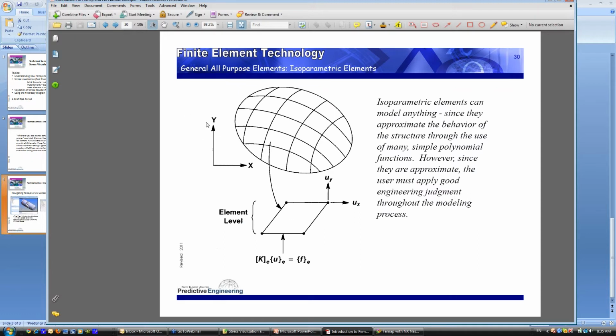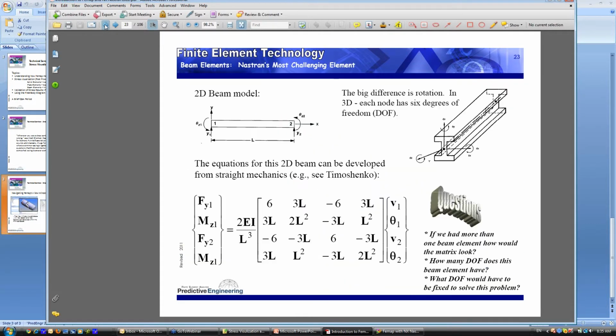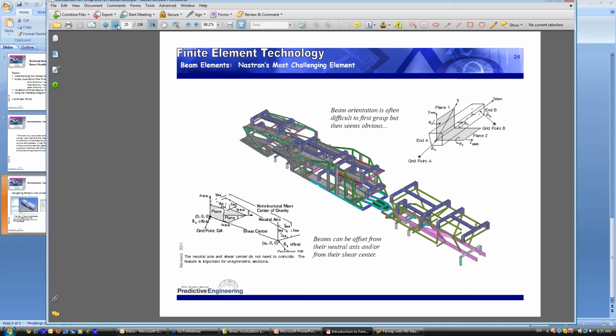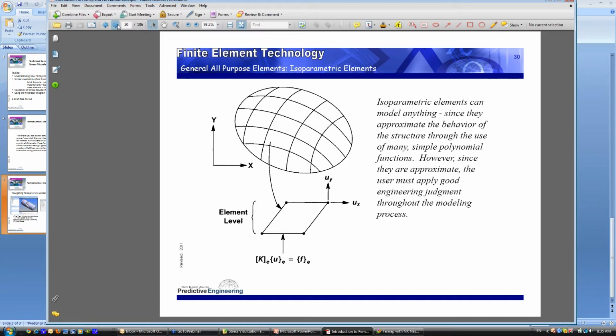Isoparametric elements. The majority of modelers out there, we're meshing plates, we're meshing solids. And then, of course, there's a few that are doing beams. And beams are exact. I'm backing up. Beams are exact because they're using exact formulation in 2D. Everything else, isoparametric elements, it's always a punt. There's tons of approximations that go in to capture the stiffness matrix of a structure because it's a finite element, and you're breaking up your structure into these finite elements to capture the deformation response. And that's done for surfaces and solids via the isoparametric element.